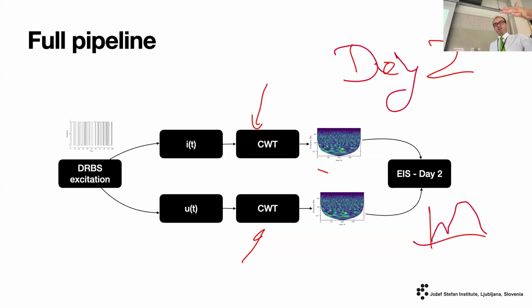To be even more flamboyant, we are not even limited in the number of points per decade. We can decide how many points we want. When we calculate EIS with this approach, we usually use something like 80 or 100 points per decade. So over 3 decades, our EIS curves have 300 points or more without compromising the measuring time.